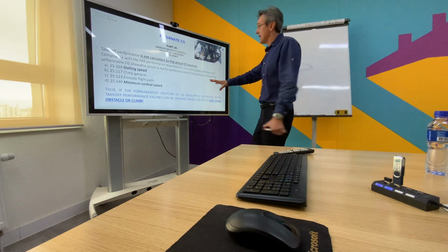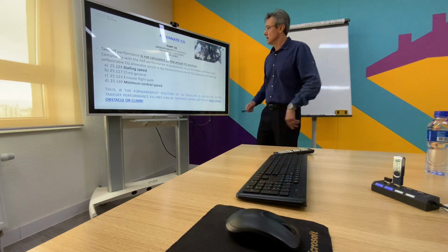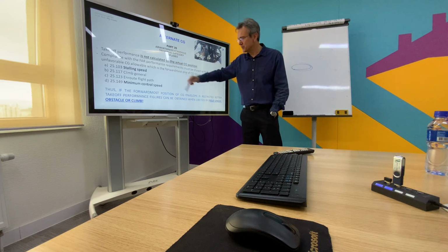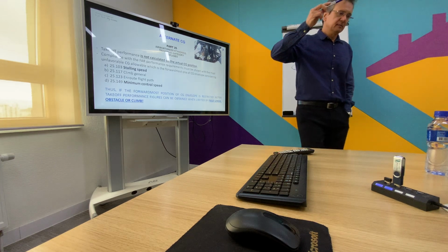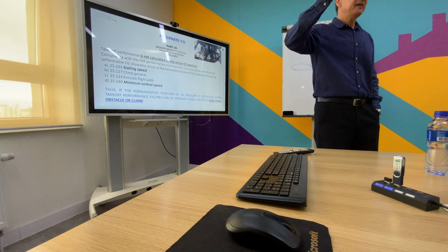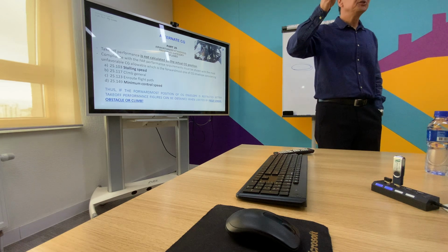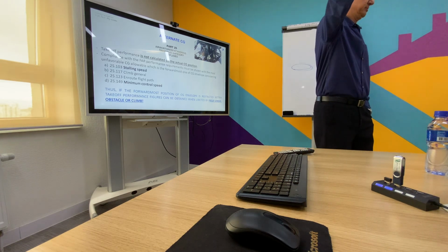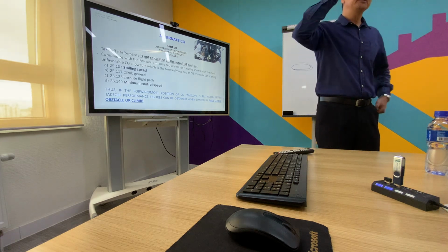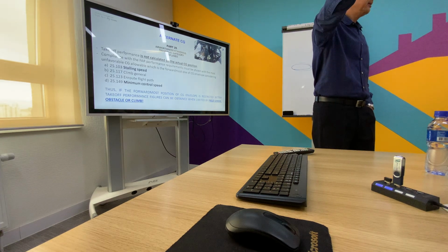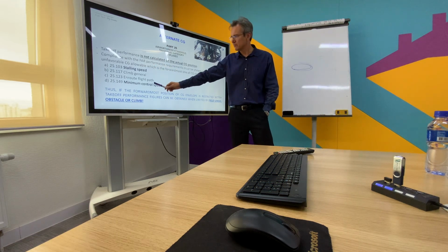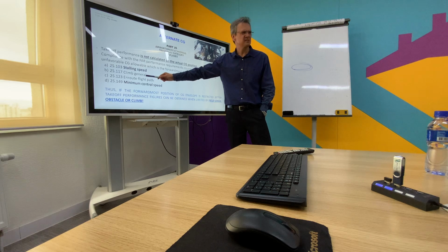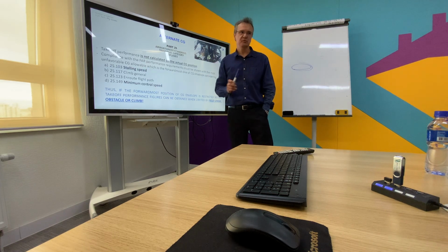And as per certification, we have to choose the worst scenario, and as per certification, they have to consider the CG forward, the worst scenario. CG far forward, okay, to get to the worst scenario regarding the stalling speeds or minimum control speed. This one and this one, sometimes they don't limit.